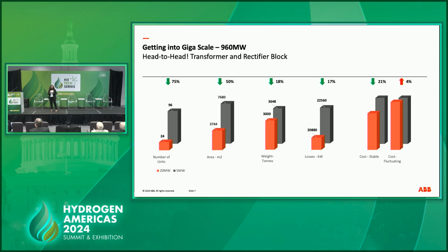But if we have something like a 60% stable grid, or even if we can keep the operating range between 75% to 100%, we can go with static filters, we can even go with switchable filters. So what we do is, when the operating range is really low, we turn off some filters. So it all depends on a really strong grid.